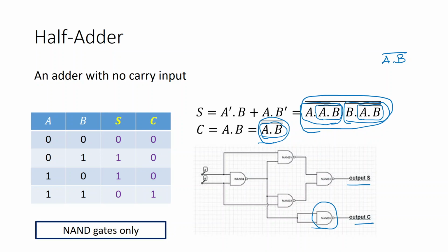So in this way, for any problem, one can ask you to implement it with only NAND gates, or only NOR gates, or only AND or OR gates, and so on. Whatever way one asks you to implement, you have to reframe the logical expression in those terms. That manipulation skill you need to develop. By looking at a few examples and doing some practice, one can develop this skill.